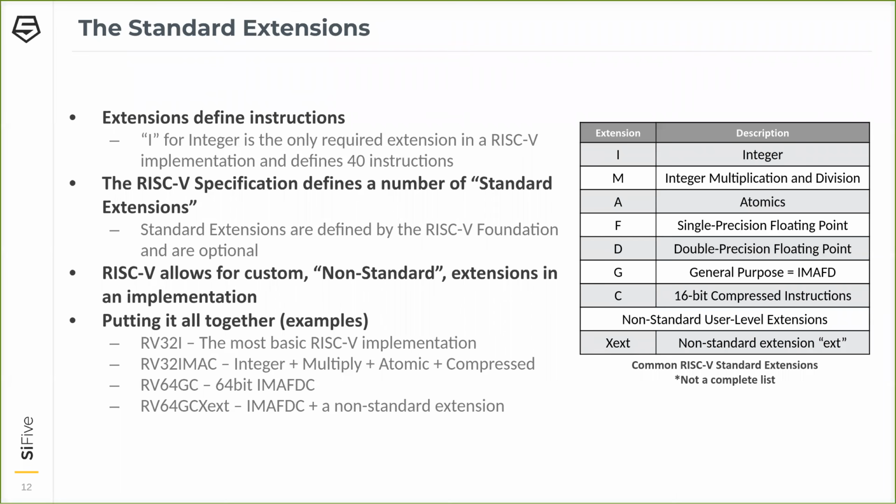Standard extensions are extensions which are defined in the RISC-V Foundation. I have some examples on the right. So the M extension defines hardware multiplication and division instructions. The A extension defines atomic instructions. F and D define the single and double precision floating point.